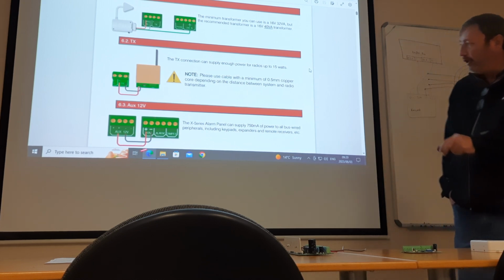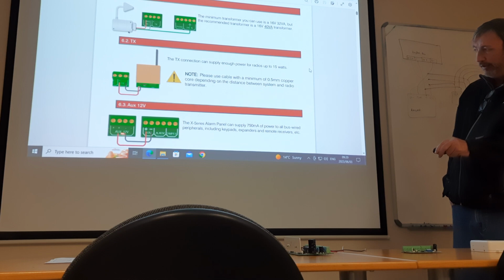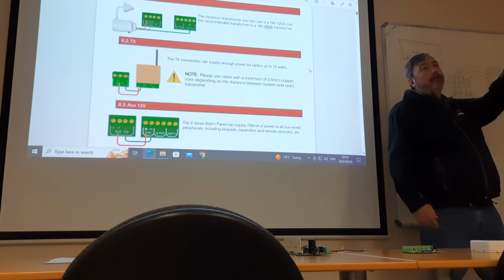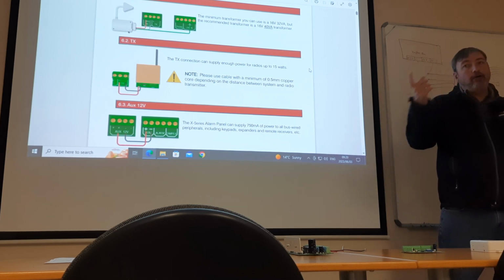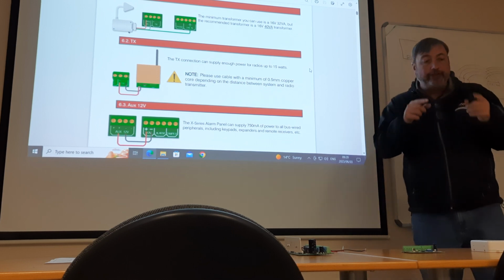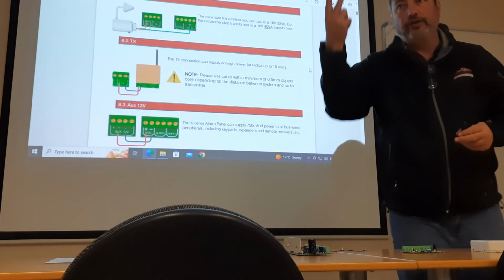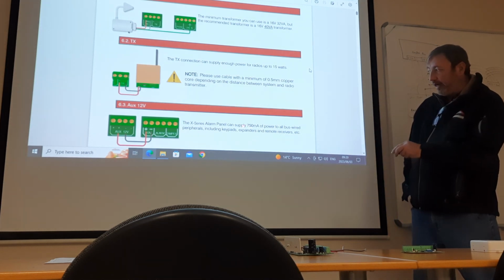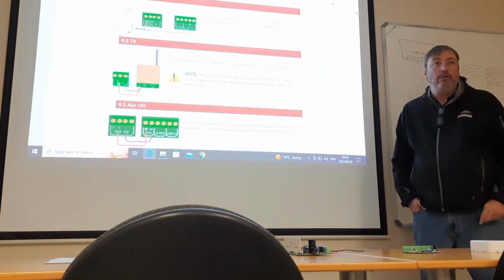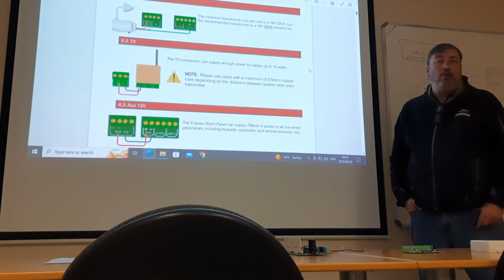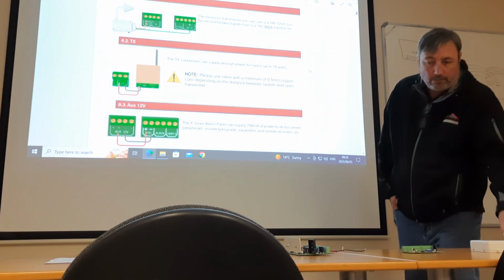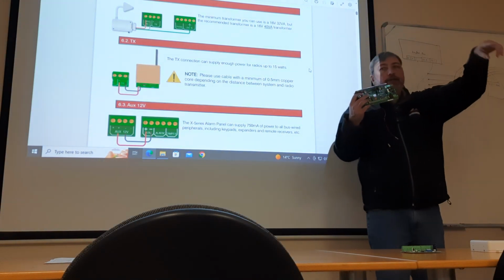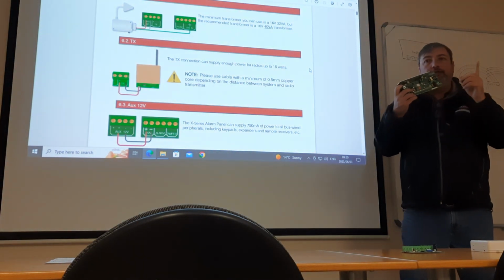And then, your auxiliary 12 volts output, you'll see there's two positives and two negative connections. Now this is where you will take the power, obviously like for your passives or all the devices that need power that you will run, except the ones that go for the keypad box, because remember the keypad box has got a positive and negative as well. And you can take up to 750 milliamps from that auxiliary output there. So what it means is, your panel can give power for your passives and all other devices that need power up to 750 milliamps.